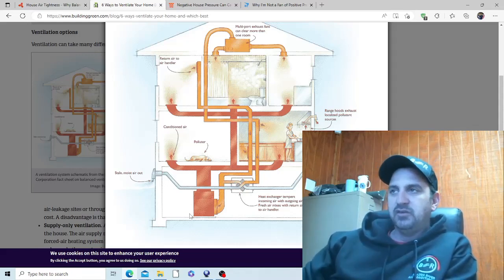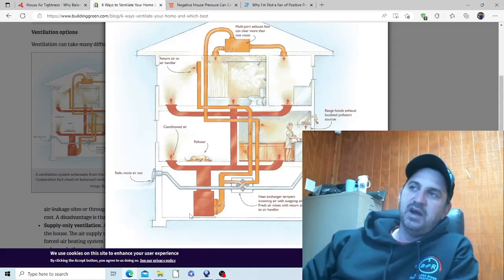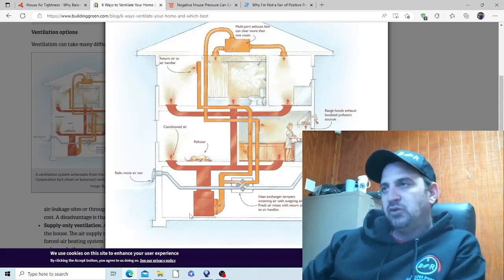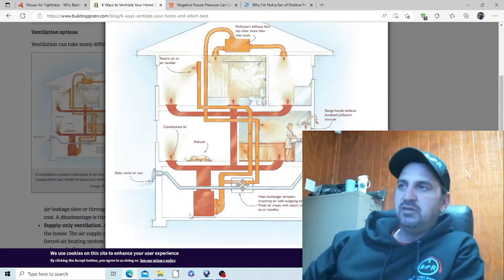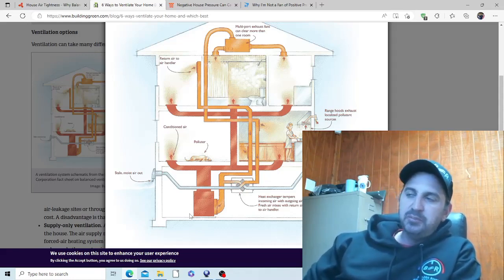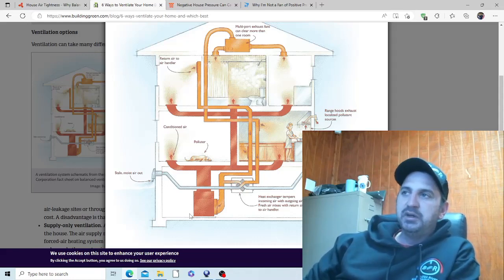insulation contractors to the HVAC contractors, and if you don't have an HVAC contractor that has taken the time and studied this stuff or doesn't believe in the fresh air intake, it gets left off of a lot of new builds. So if you're doing a new build or a renovation and you're using spray foam, your insulation contractor should tell you to properly ventilate. But if they don't, make sure you ask your mechanical contractor to include it on his bid. This is one thing you don't want to leave off.